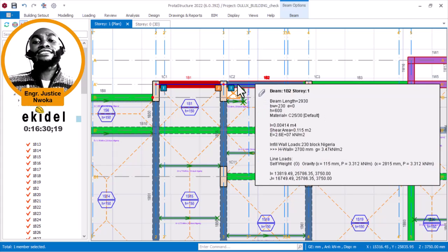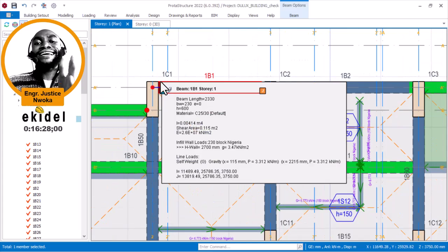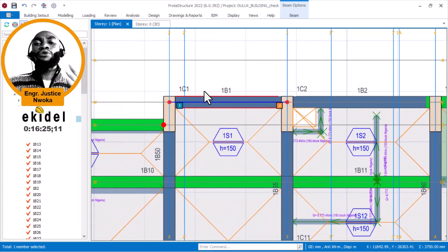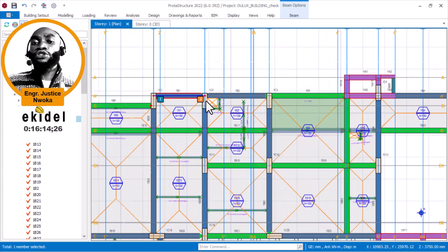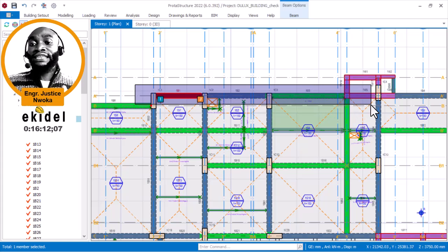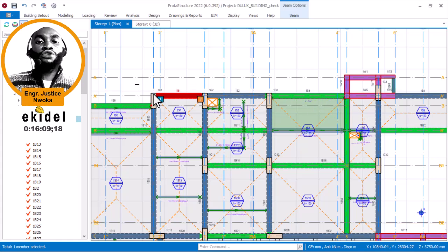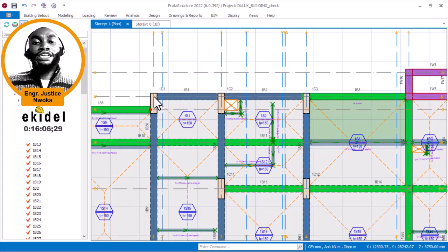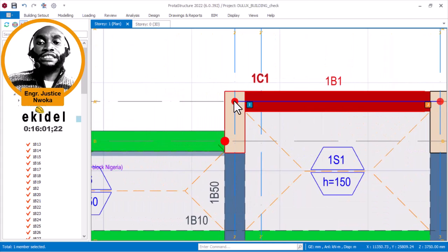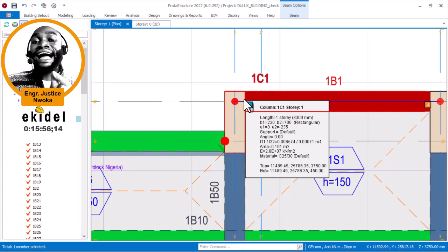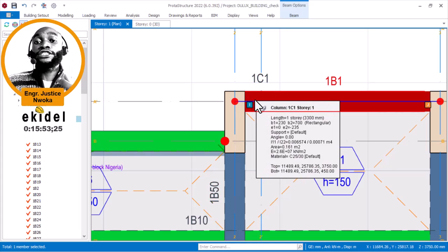In this case, the next thing I'll show you is how to hinge this. Knowing that every end of a beam is to carry 0 moment, on this continuous beam, because this is a full beam, this end here, which is this beam here, since there is no continuity after this column, this beam 1 at this end becomes a hinge end or a pin end.